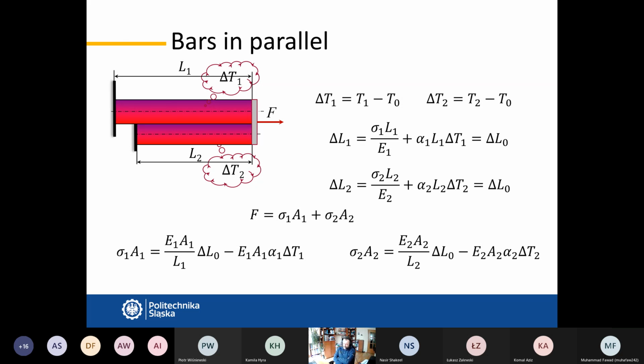We have discussed that the spring force is a linear function of the deformation. So you can reduce, not completely eliminate, the force or stress produced by the temperature increase or decrease, but you can reduce it significantly, of course, depending on how stiff the spring is.